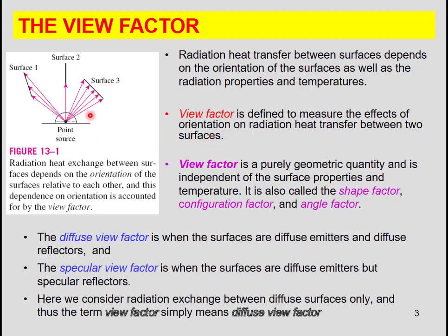And as you can see here, view factor is a purely geometric quantity, and it is independent of the surface properties and temperature. It is only dependent on the geometry and actually the orientation of each surface. So it is also called the shape factor, configuration factor, or even angle factor.